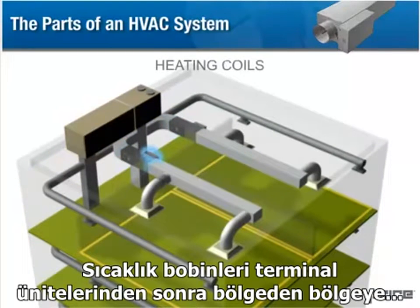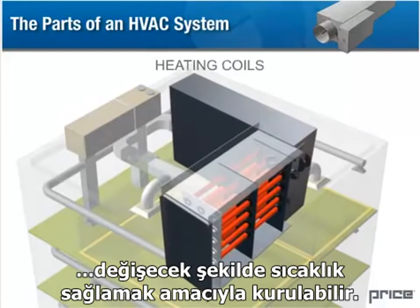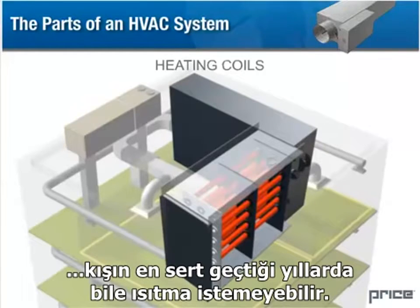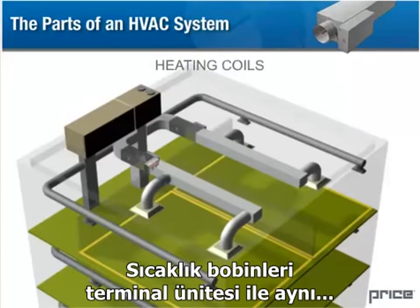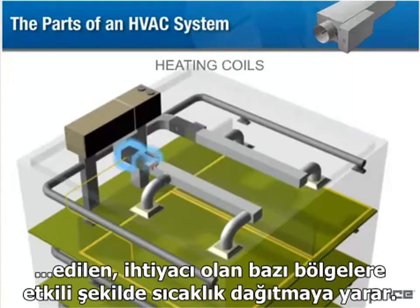Heating coils may be installed after a terminal unit to provide heat on a zone-by-zone basis. As mentioned previously, buildings with a high number of occupants may not require extensive heating even during the coldest months of the year. Heating coils offer an efficient way of providing heat for those few areas that require it and are controlled by the same thermostat system as the terminal unit.